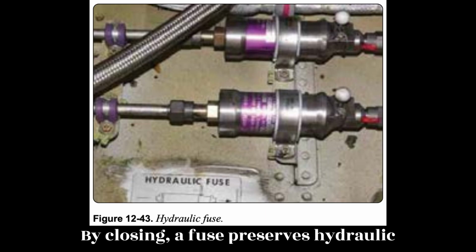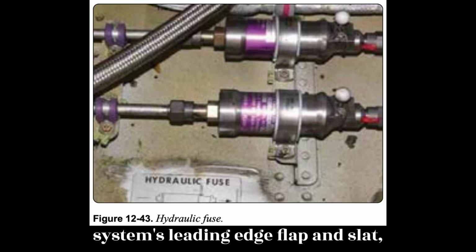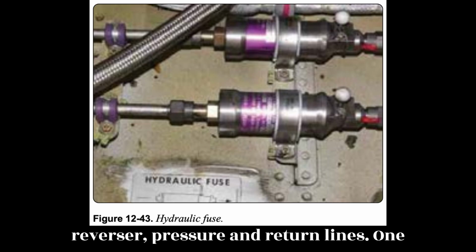By closing, a fuse preserves hydraulic fluid for the rest of the system. Hydraulic fuses are fitted to the brake system, leading edge flap and slat extend and retract lines, nose landing gear up and down lines, and the thrust reverser pressure and return lines.